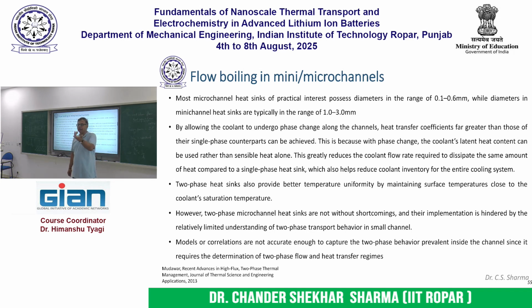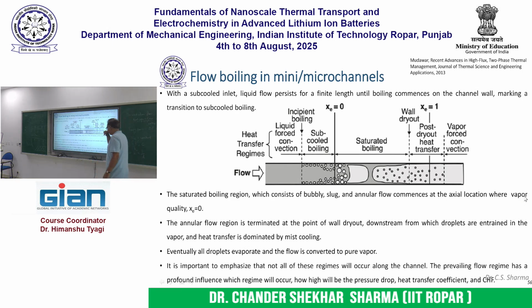So beyond evaporation, a lot of work has also gone into flow boiling. Let's say I was talking about single phase cooling where liquid is flowing in the channel. How about if, as it flows through, it also undergoes boiling? Then you can absorb much higher heat flux, right? We all know this, but it has not yet been commercially implemented. So what are the bottlenecks there? The main issue is how the nature of flow changes in the downstream direction.